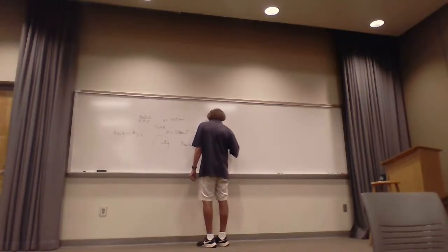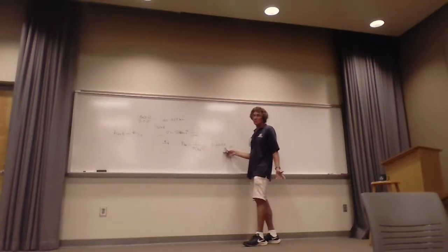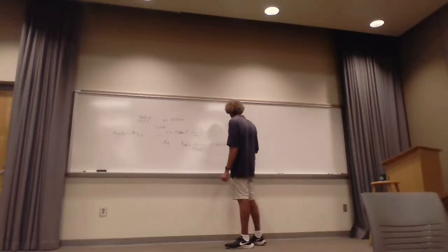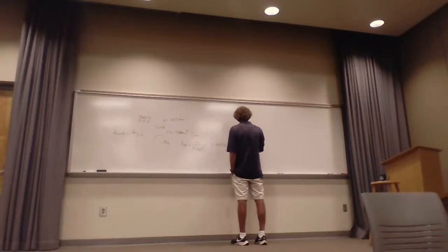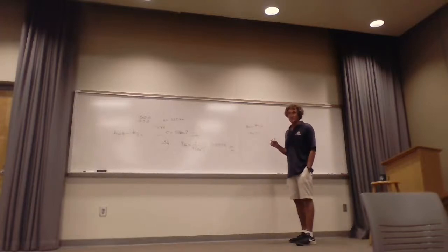0.0878 ohms per meter. All right, so it's 87.8 milliohms per meter, right? Agreed? Per meter. Now, let's find out what it is for this, only we'll do the AWG number 20, but now we'll go 19 by 32, right? Yes, sir. I'm gonna show you something else, guys.